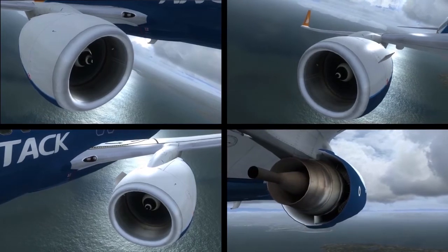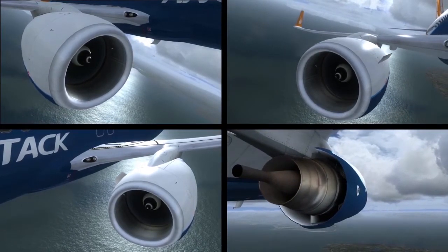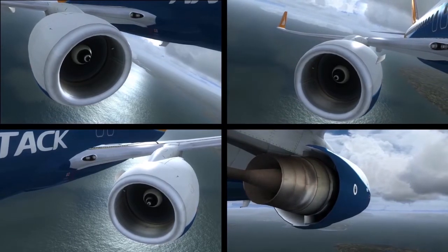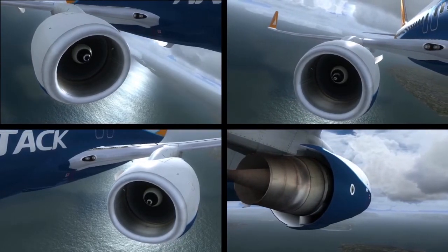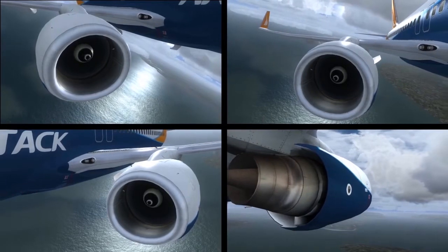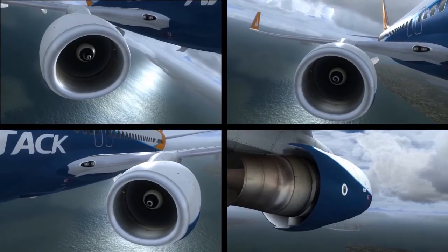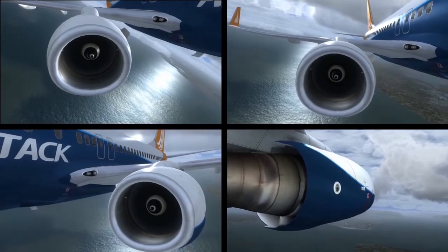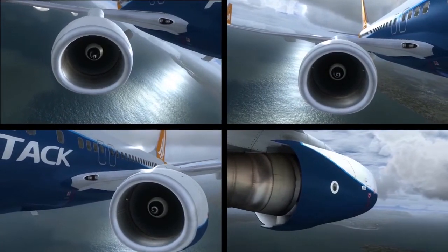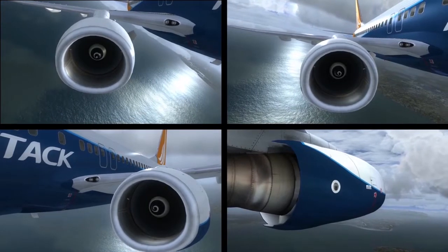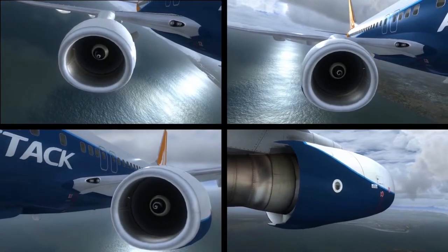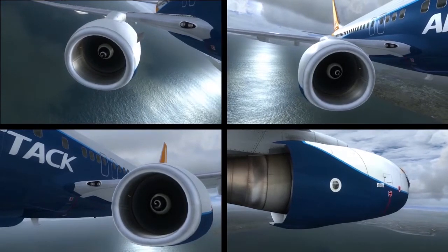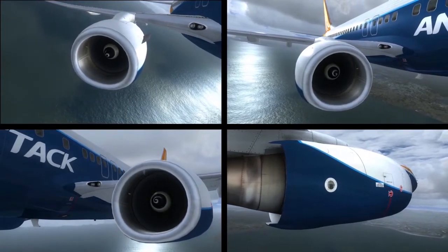switch position. When the engine hydraulic pump switches are selected off, a solenoid valve closes and stops the pumps from transmitting pressure to the rest of the system. Because the engine-driven pumps are mounted on the accessory gearbox, there is no need to select the engine pump switches off on shutdown. It is actually advised to leave the engine pump switches on during shutdown to prolong the life of the solenoid valve. The electric hydraulic pump switches simply provide and remove power to the electric pumps.